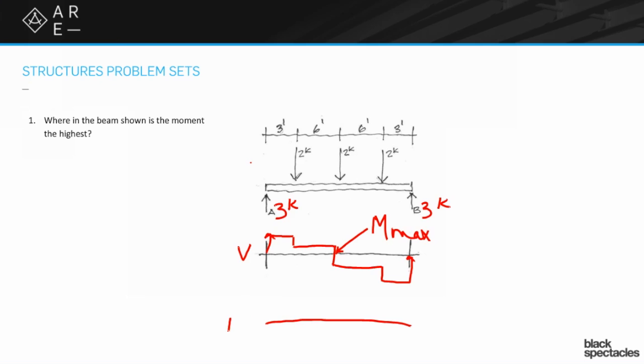So yes, we are going to draw that moment diagram, and you need to know a couple of different things that I'll describe along the way. The first is to figure out what number you're going to go up to. We're going to do the area underneath this shear diagram. So we basically have a 3. We went up 3, so this value here is 3.